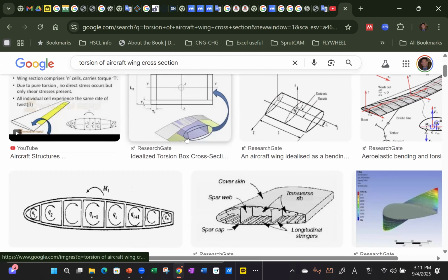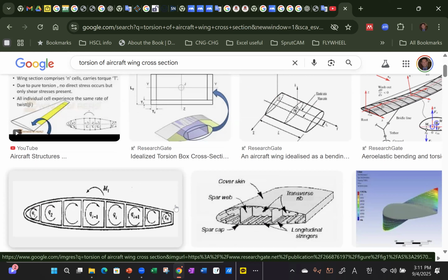are, as you can see, very thin wall structures. The wing of an aircraft is not solid, it's empty in there. Why empty? Well, the outside geometry is nothing but to control airflow. Velocity difference causes pressure difference, and that is the force we lift up with. So it doesn't need to be solid inside because the air doesn't go inside, the air flows outside. So the outside of the structure is important, and to make the structure light, the inside is empty.